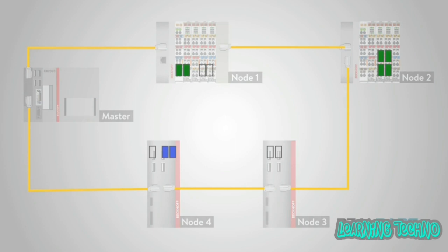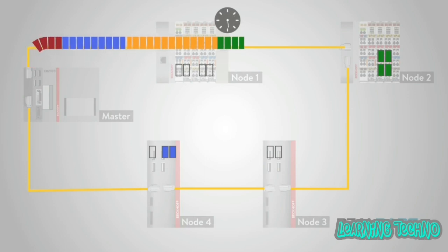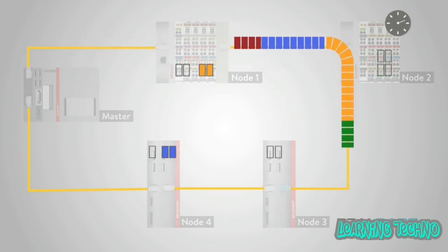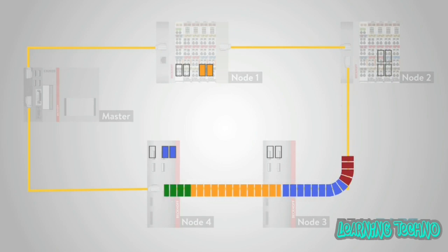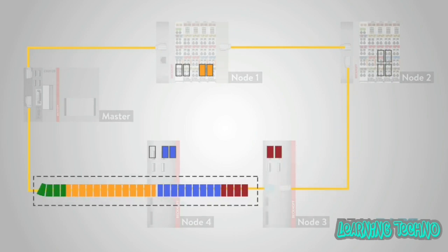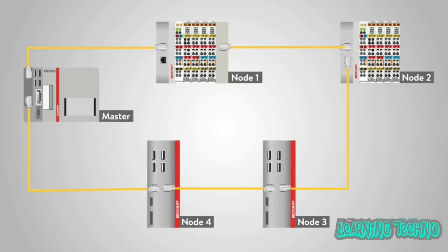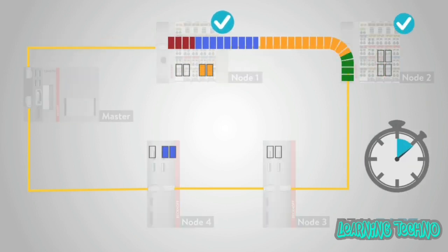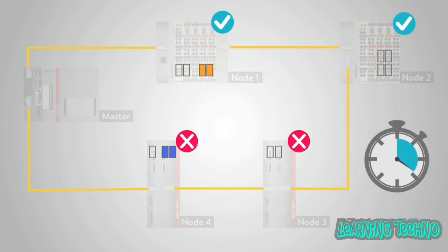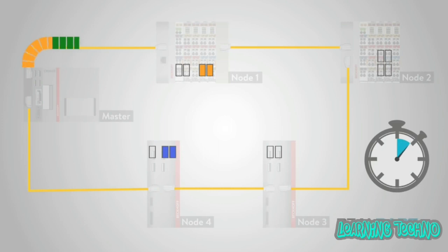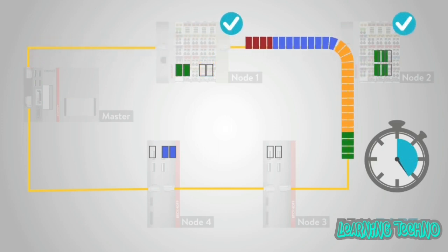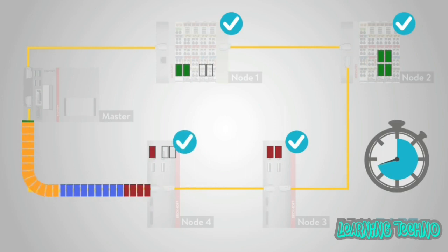The processing of the data on the fly in the hardware of the device is a major advantage of EtherCAT. Although there is still a small delay in the data frame as the device adds its data to it, it is greatly reduced by the often single data stream of EtherCAT versus the multiple Ethernet frames used in an Ethernet network. This advantage can also be a disadvantage. Many devices may not be able to handle these highly decreased cycle times, and the EtherCAT network may need to be slowed to accommodate these devices. Since the EtherCAT network can be slowed, mark the disadvantage as an advantage once again.